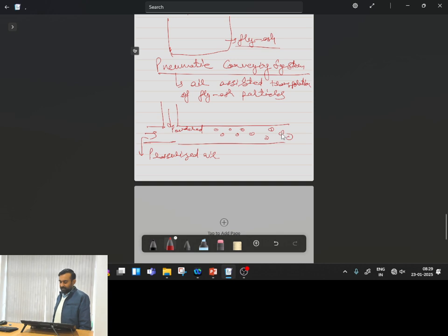So typically in a power plant, the boiler is located at the core of the plant. From the boiler location to somewhere near the boundary of the plant, a pneumatic conveying pipeline is there, and this pipeline puts this ash in some silo, and from the silo this ash is transported in trucks to the applications where it is needed.